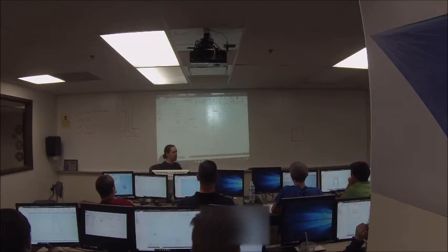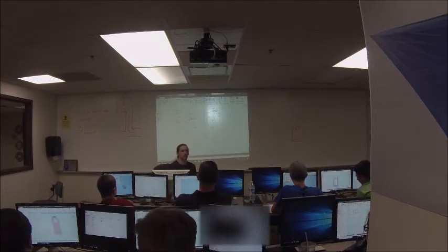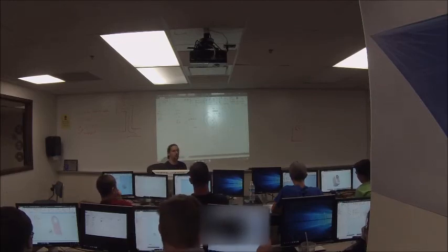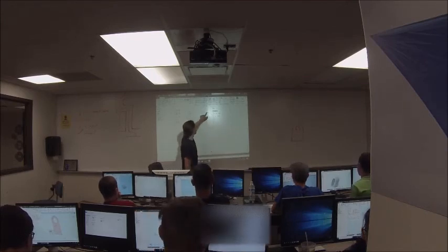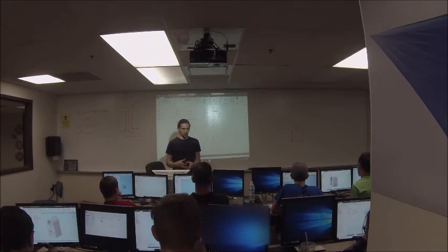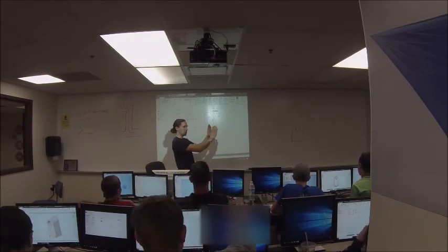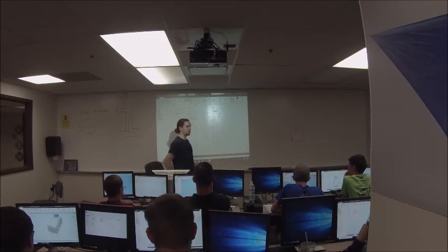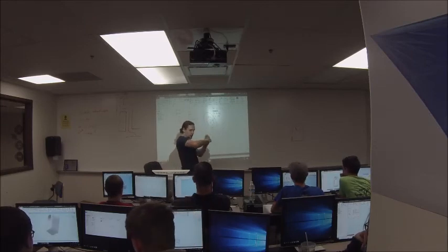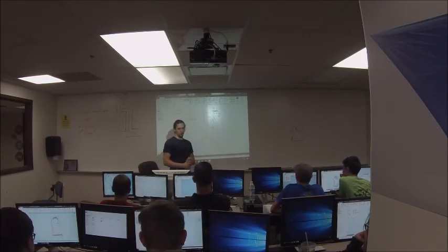The reason for that is when you're creating a sketch, you're creating what are called profiles. Each profile is highlighted in green. So this is a profile. A profile is basically a closed loop. It has to be closed. You can't have a U shape made out of lines. That's not a profile. Those are just lines. But if I close it and make it a closed shape, that's what's called a profile.